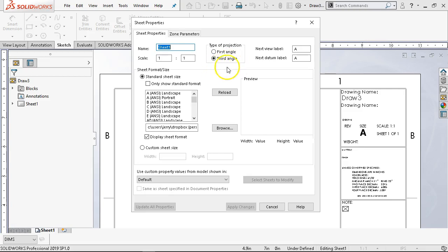My description of first angle and third angle is what is stationary. Right? If the part is stationary and you are moving around the part, that basically becomes first angle. So you're looking at a view that you're calling your front view. As you rotate left, that becomes the view that ends up on the right side because you're now looking from that side. All right, so to most of us, that's going to be backwards. We were taught third angle.